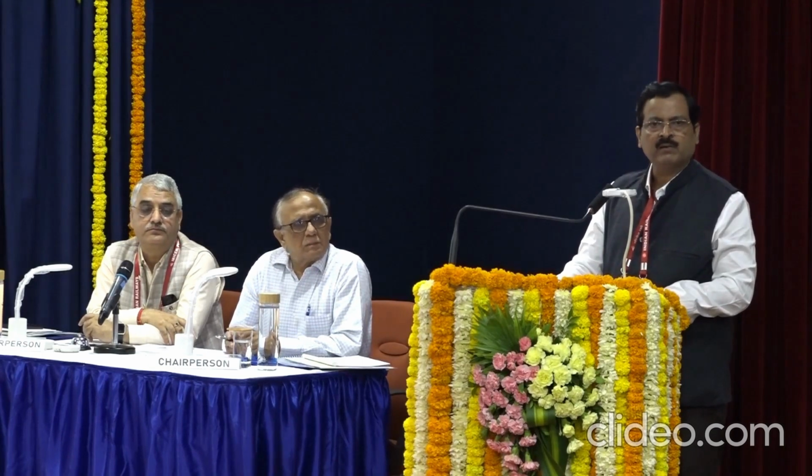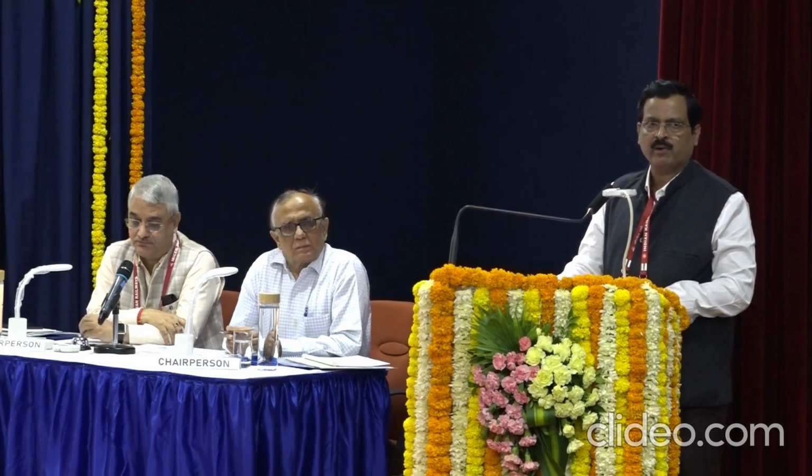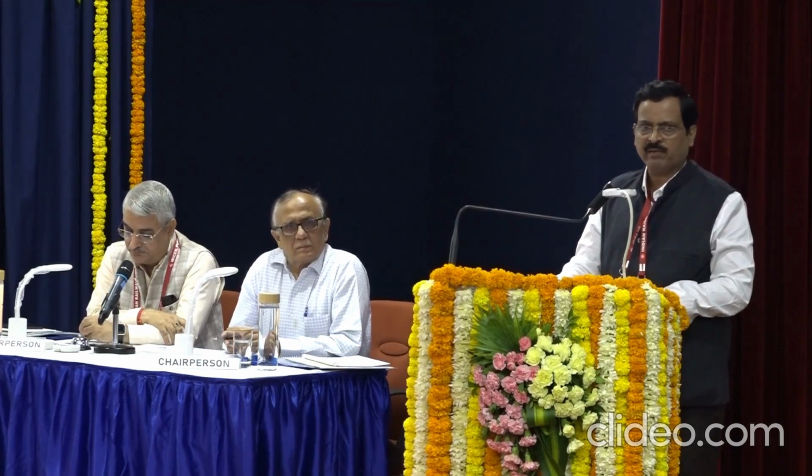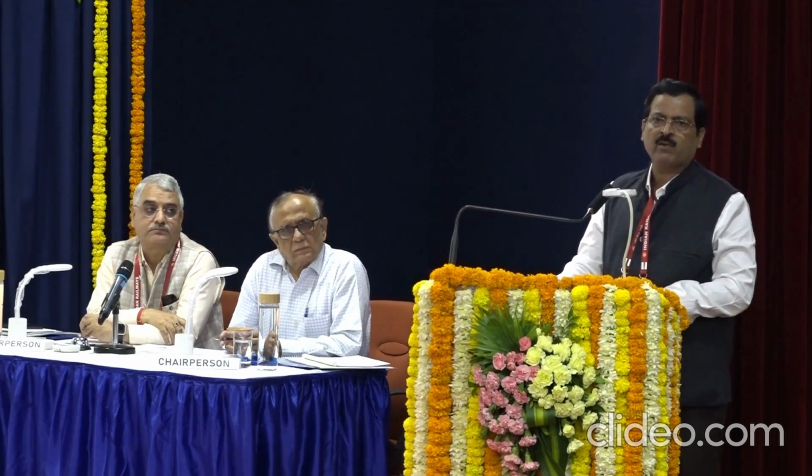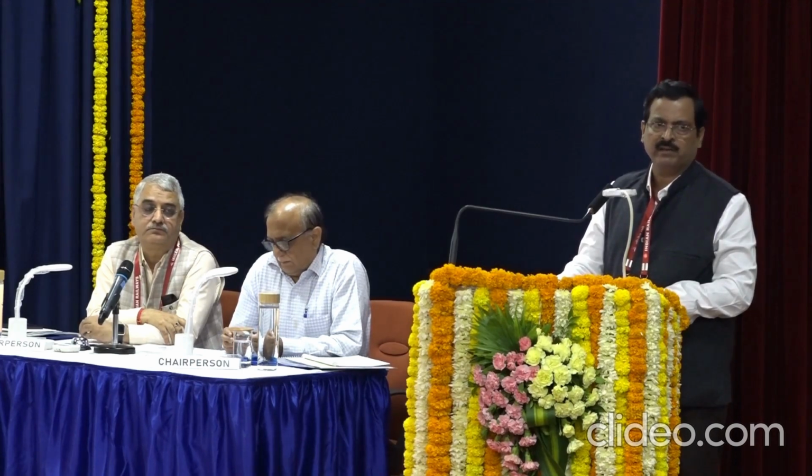What we have done, for dynamic analysis, we need three parameters: vertical displacement, deck acceleration, and end rotation. So far, there are no IRS standards available for that. We have taken up a project with IIT Roorkee at a cost of 1.78 crore. They are doing the dynamic analysis of all 72 standard spans of RDSO. At the fag end, they will develop a guideline. They will define the limiting parameters, the permissible values of these parameters, and we will go ahead. The guideline will be developed at the end. Thank you.